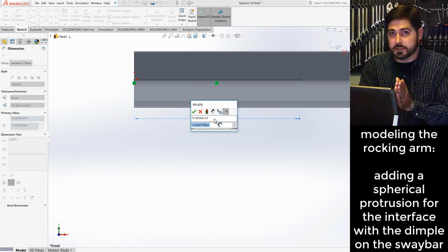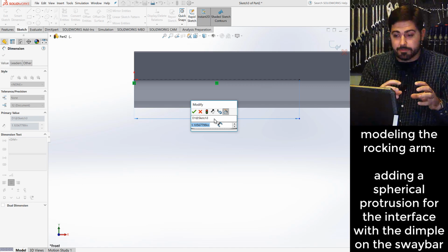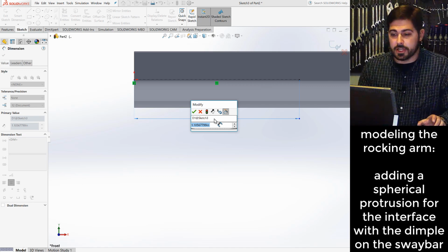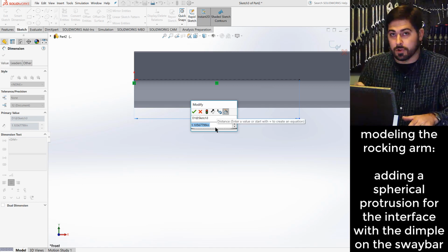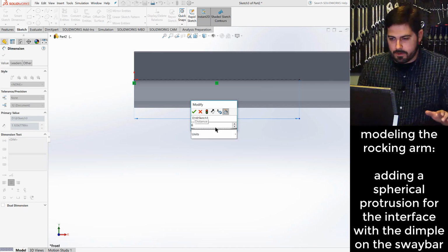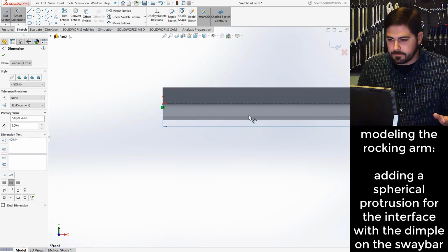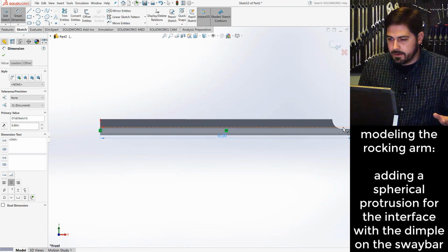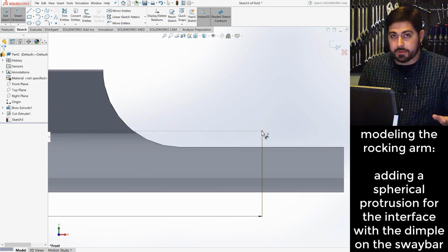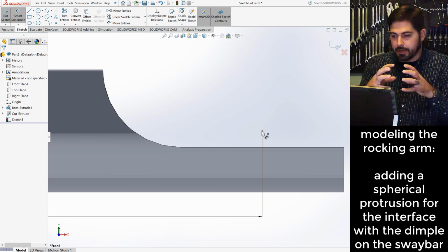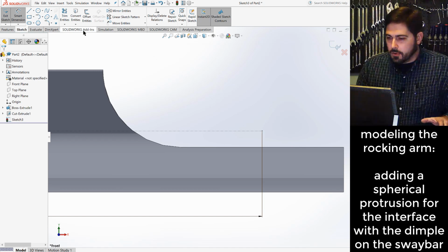Now this is actually going to specify that literal center of the ball where the interface happens between this part and the U-shaped piece. And so I want it to be right at 6 inches. I don't want this one to overlap at all. Okay, so I want 6 inches right there. And when you take a look at that, it puts a nice point right here that can become the center line of me building a little spherical ball. Essentially, it's going to sit right here.